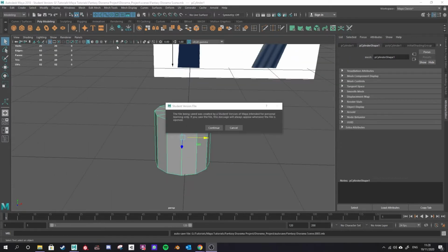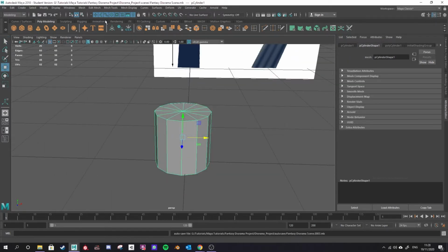The shelves here will have all of your tools, and you can quick select them using the little icons here. You can also use the tools on the left hand side. So for instance, the selection tool there can be Q on your keypad, or you can use this arrow icon. W will be your move tool, which is highlighted here. E is your rotate tool, and R is your scale tool. Try to get used to using the keyboard shortcuts for these, but they are available on the left hand side of your screen as well.